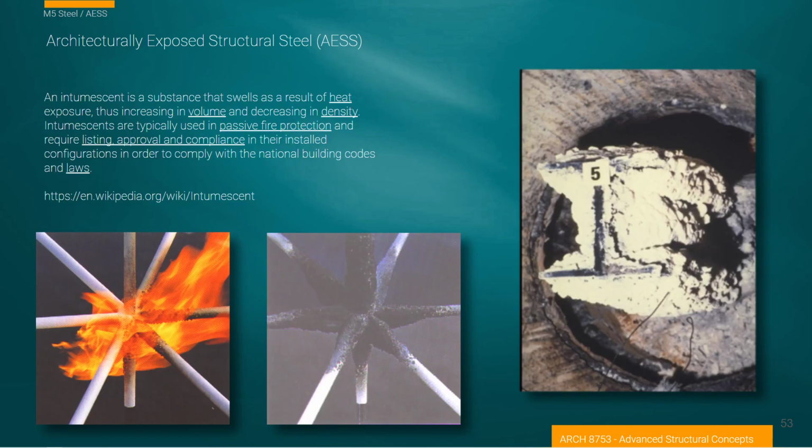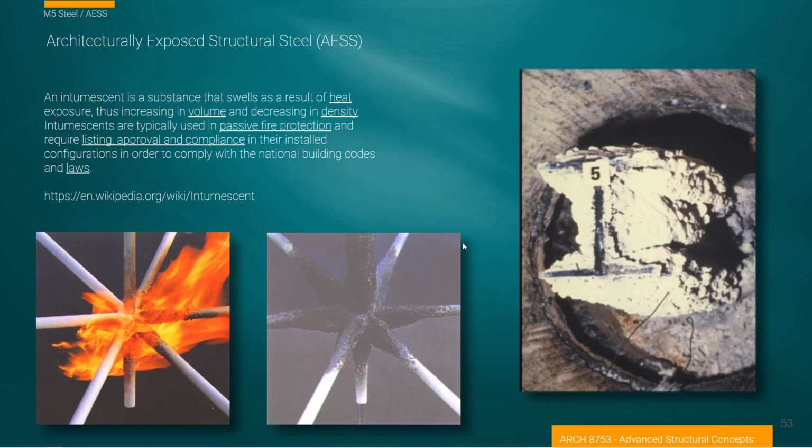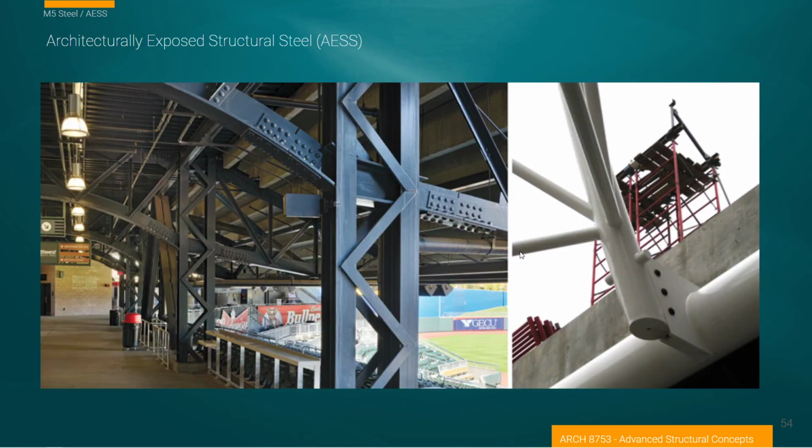And that's funny, that one's appearing again, but as a healthy reminder that if these are exposed and we don't have fireproofing, there is a method of actually applying a paint that will be fire protective. And just another few examples of exposed structural steel. Once again, I find the bolted connections are obviously very nice. These would probably be very difficult because these are actually riveted. This is probably an older structure, so we're not seeing bolts here, but we're actually seeing rivets.